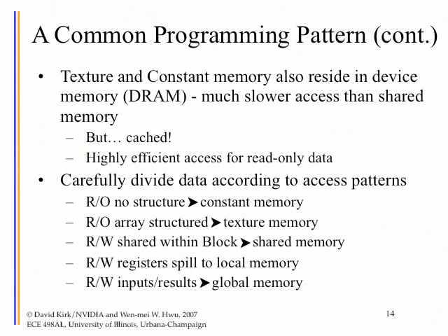So what you would do is you would use the constant memory and initialize a variable in the constant memory. As soon as you use it, it's going to be implicitly brought into a cache. Okay, and that cache actually has a very high fan out from each location to all the streaming processors in the same 8 processor unit. And that broadcast mechanism will allow all the threads to access that same value in one clock cycle. And that can give you very high efficiency in accessing these.